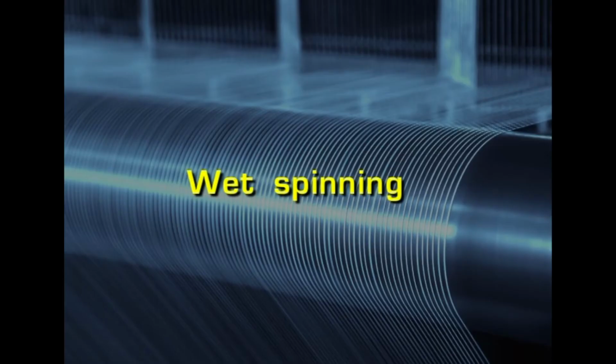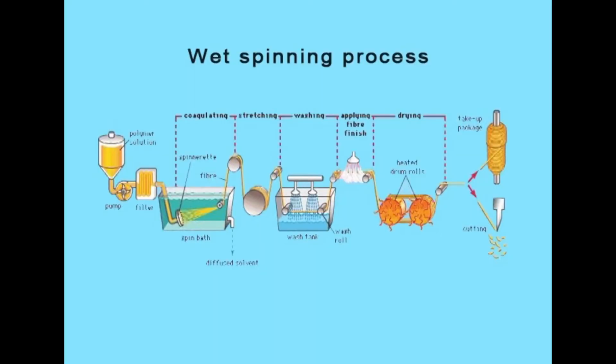The third method of chemical spinning is wet spinning. When the polymer is not in a stage of melting or dissolving in a volatile solvent, then a non-volatile solvent is employed. Since a non-volatile solvent is used, we cannot evaporate it, and so a chemical bath is required in order to coagulate the polymer, so that it comes out in the form of a thin filament.